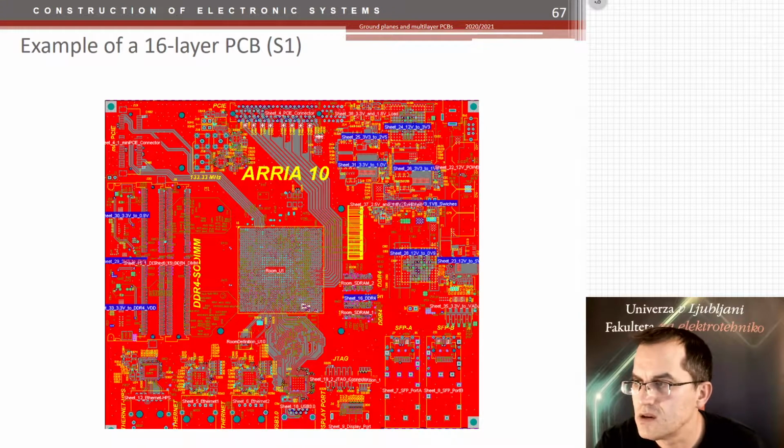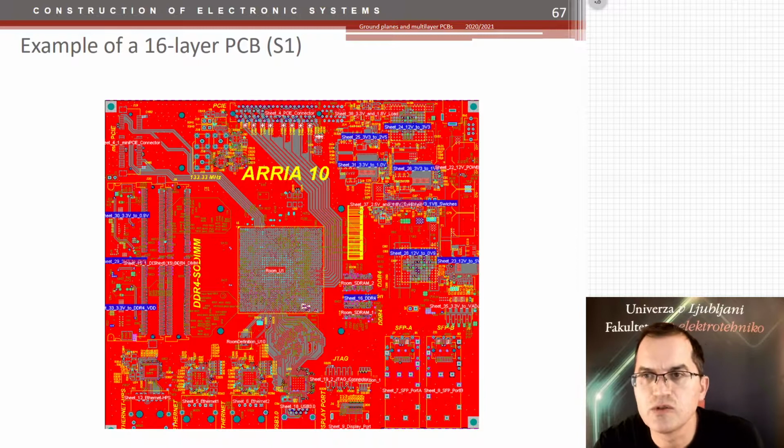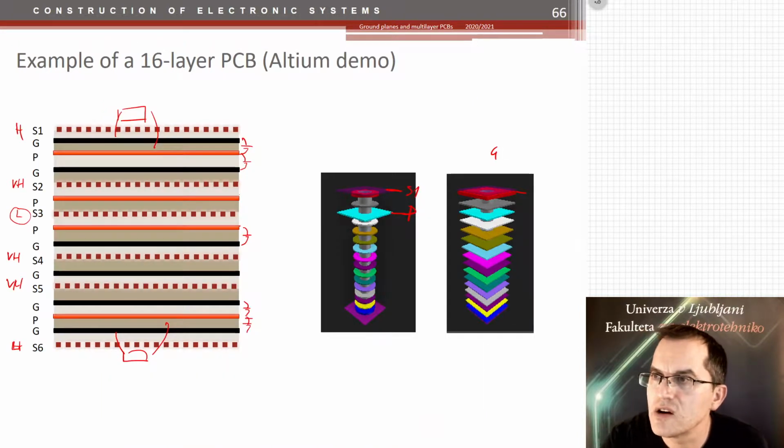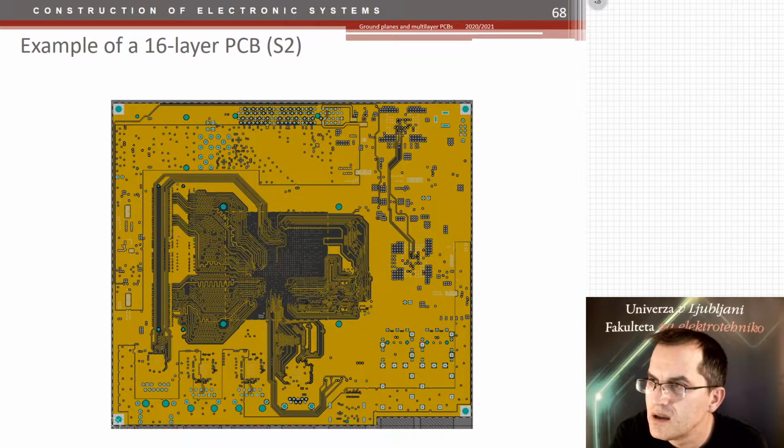Now let's go. Display port is also there. These are display lines, display connection lines. Let's go to signal layer 2. Signal layer 2 is actually on layer 1, 2, 3, 4, 5. Here. That's signal layer 2. Now we have connections to the memory, the DDR memory here and there, and also Ethernet, one Ethernet.